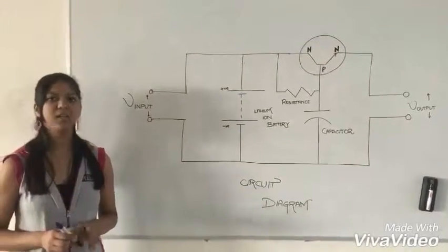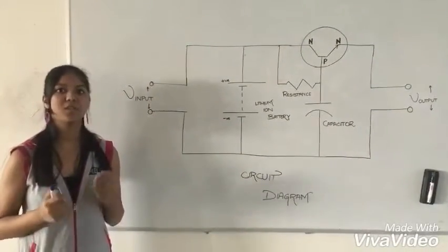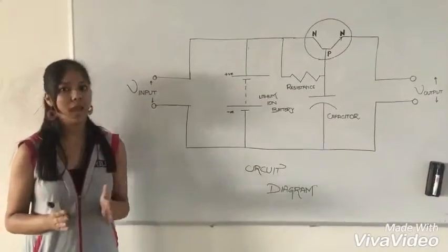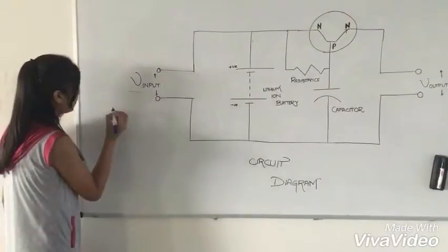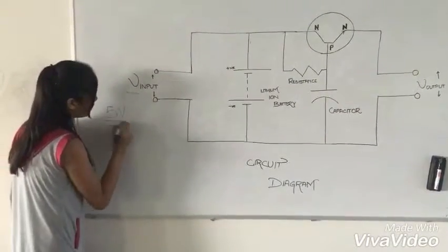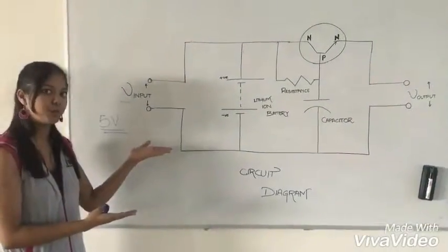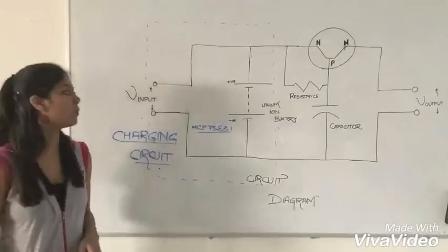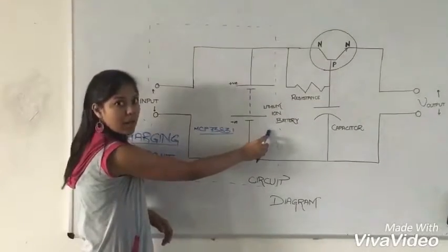In the charging circuit, a power bank is externally charged using a standard USB charger. Due to international USB standards, we take the V input to be 5 volts. Obviously, we can make this value higher, but we'll have to program our circuit accordingly. In a charging circuit, let us first talk about the major component, that is the lithium-ion battery.